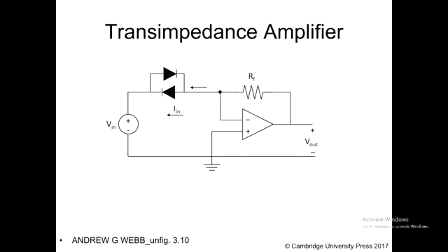Two advantages based on what we've discussed. The protection for the fact that it's back to back. Yep. Good. And something else to answer the next part: it can operate in both directions, basically. So that can be a detector for infrared and red, respectively. So we could use that for our pulse oximeter circuit. Good.